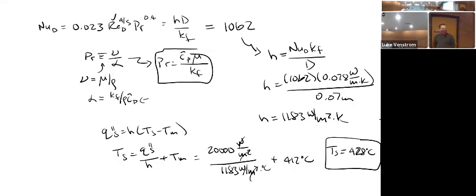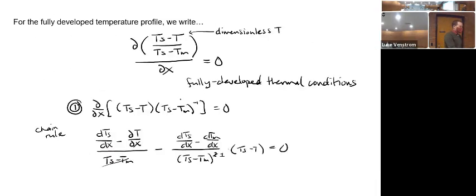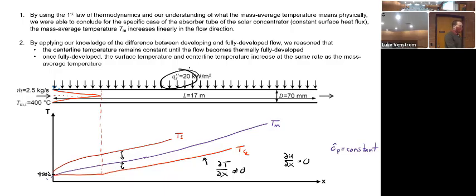So it's not that different from the average temperature of the fluid. It's only 14 degrees higher. The surface temperature is 14 degrees higher than the mass average temperature of the fluid. But this also represents the max temperature of the fluid. So that seems reasonable. All of this only applies to conditions in which we know the flux and it's given.